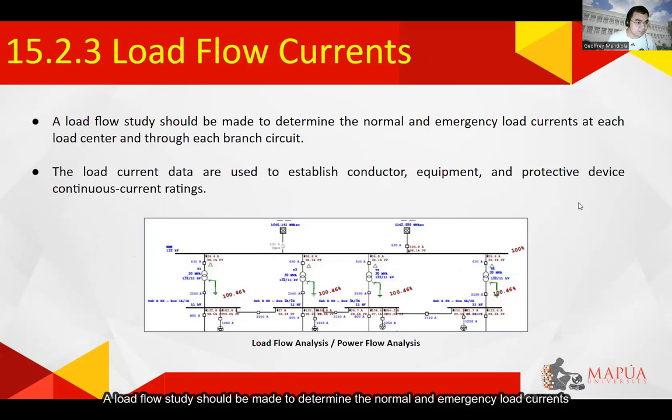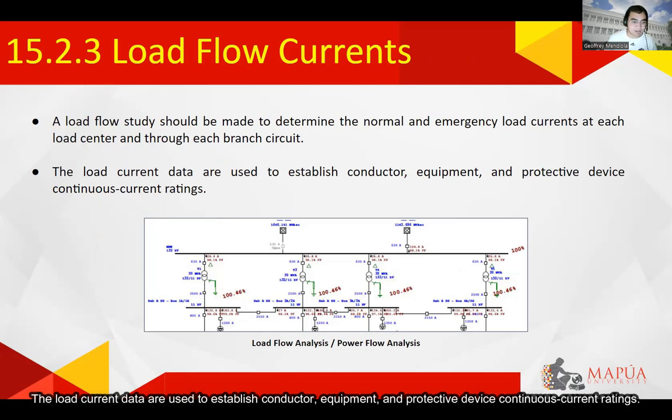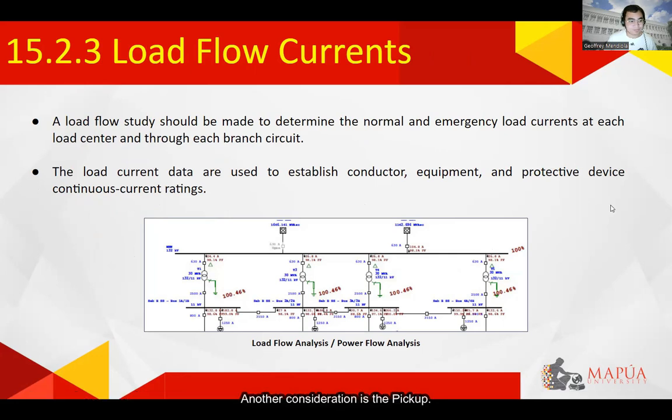A load flow study should be made to determine the normal and emergency load currents at each load center and through each branch circuit. The load current data are used to establish conductor, equipment, and protective device continuous current ratings.